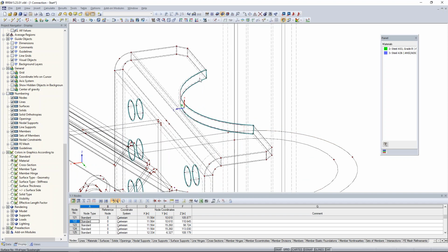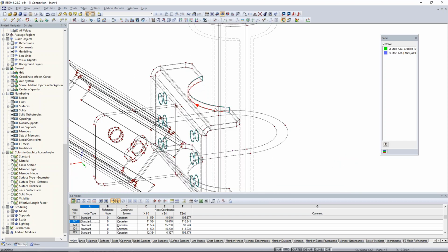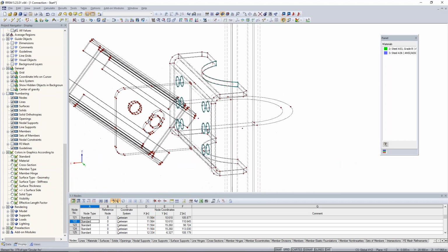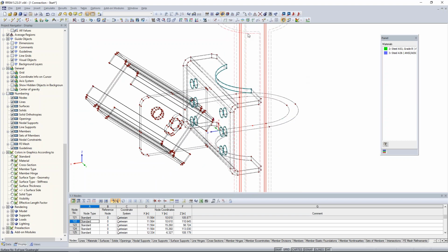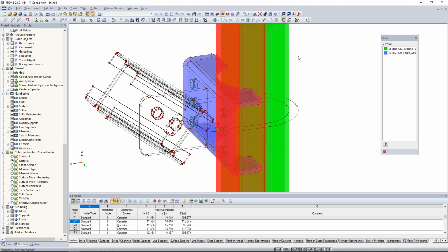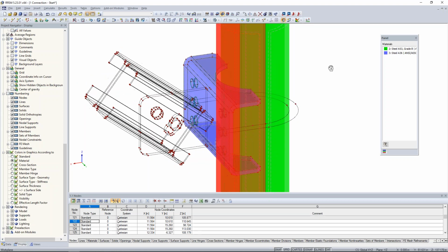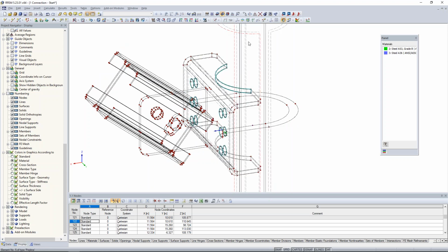Now this surface still exists in the interior of this plate element. So we'll take this a step further then, and what we'd like to do is to double click, and actually let me back up a step. We'd like to double click on the null surface. Remember, this is part of the pipe here. It might be a little bit easier to see when we are in a rendered view. We'll change this back to a wireframe view.